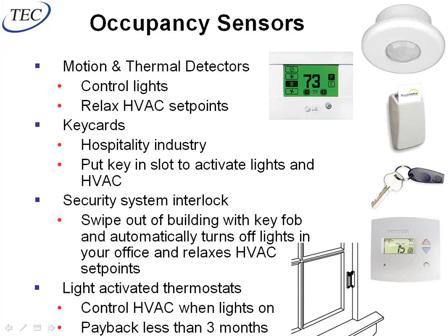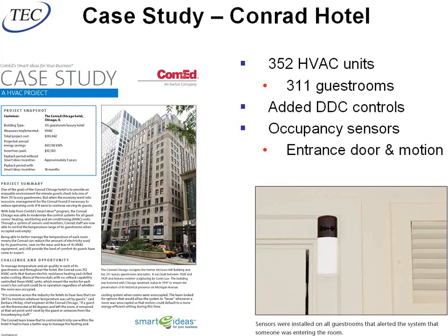And then the last way to do this kind of thing, if you have buildings that have operable windows, which is fantastic. If you want to have natural ventilation, awesome. But if you got natural ventilation going on and your window's open, why am I also giving you mechanical ventilation? No, I'm not. So you put those little sensors on the window. They look like the security sensors you might have at your house. The window's open, the sensor opens, tells you you don't get any HVAC, any ventilation, right? Windows open, no HVAC. Windows closed, yes HVAC. It's that simple.